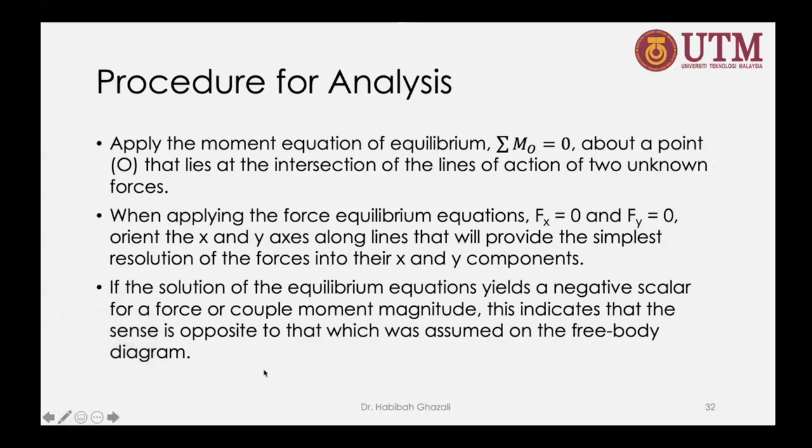Okay, so if the solution of the equilibrium equation yields a negative scalar for a force or couple moment magnitude, this indicates that the sense is opposite to what you have assumed in your free body diagram. I'm sure everyone knows this as well. If you draw your free body diagram, you can assume the direction of forces in your free body diagram, whichever direction you want. Okay, so let's say this is my free body diagram.